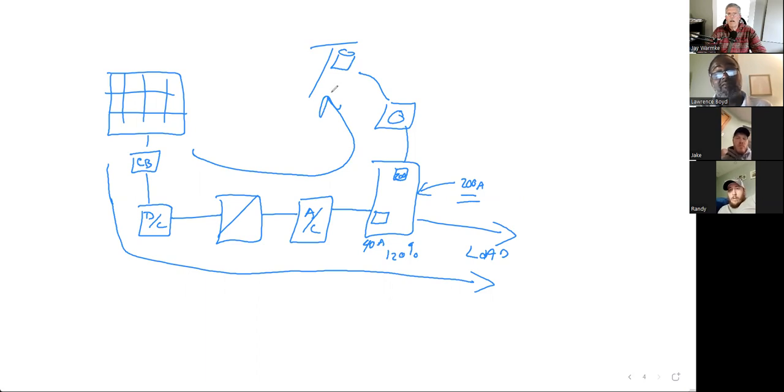Yeah. So basically, my inverter doesn't care what the load is. Right? In a standalone system, all of the load's power is flowing through the inverter. But in this case, only the load that is being serviced by the array is flowing through the inverter, because some of it comes straight from the grid, right? If I need to.